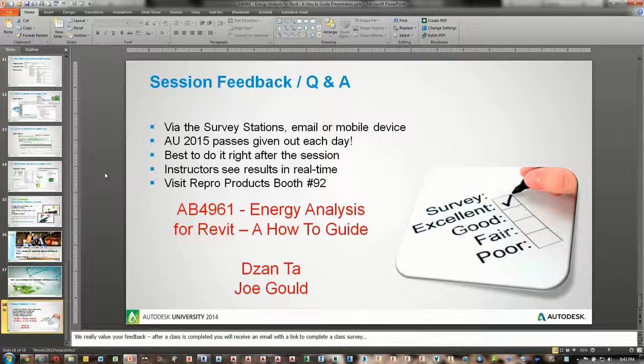And with that, you have the ability to change those materials per side without having to model any of those details. So you can actually take that, and like Zahn was showing earlier on more of a building enclosed envelope session, you can also do the very same thing via subscription on a conceptual level. Rather than placing zones and things like that, it'll take into account conceptual construction. Since there are no walls, doors, or windows, it's going to conceptually make some assumptions as to what our value is, and it will spit out a number.